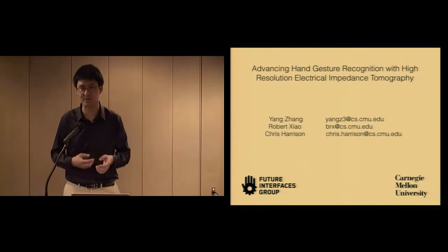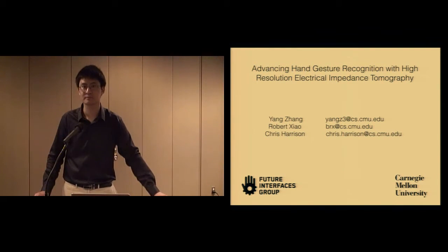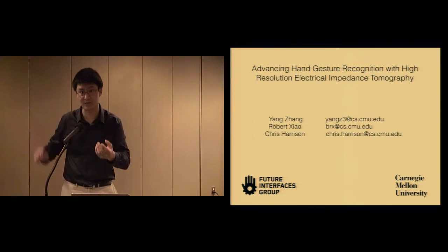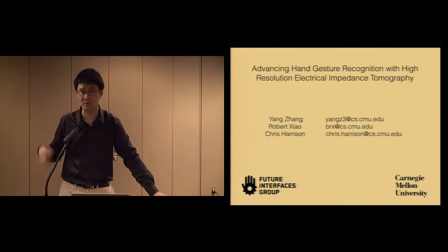You can sense factors beyond that, and those can tell you things that EMG sensing might not directly be able to tell you. So do you think you could get more fine-grained information about the finger movement? Yes. For example, when we move our fingers very, very slightly, we can actually see differences in the reconstructed image, and that's why we'd like to explore if we can actually do things like hand pose. We think that's possible with something like EIT, where it might not be possible with EMG.